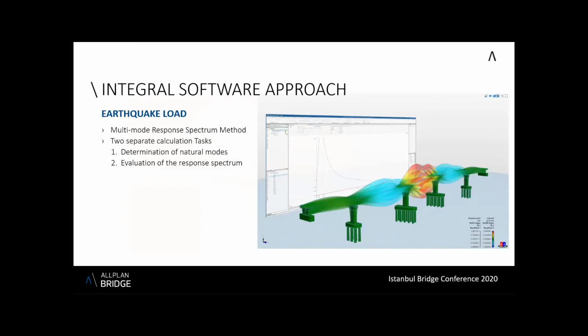So the next important implementation is the dynamic analysis, the earthquake load evaluation, because a dynamic analysis is required for considering the effects of earthquake events, for example, the dynamic vibration behavior of the structure, and it must be investigated. This extension of the structural analysis feature is the most recent functionality, and the modal analysis method has turned out to be the appropriate method for determining the relevant response behavior of structures in earthquake situations.